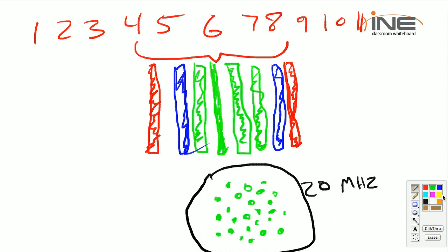Well, it's not serialization, but similar to that. Less time transmitting. And then I've got all these guard frequencies, guard subcarriers. And I've got some control subcarriers as well. So they're guarding against interference and they're controlling the overall signal.